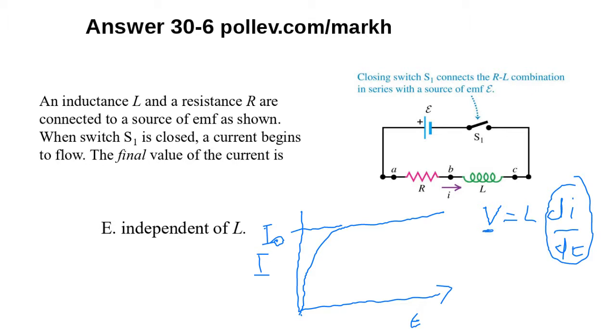And then when we've got no change in current, the inductor isn't doing anything, right? An ideal inductor, if we've got a steady current that's been steady for a long enough time compared to its time constant, may as well just be a wire, because we've got this di/dt component for the voltage over an inductor. It's got no voltage over it, so its inductance doesn't count for anything.